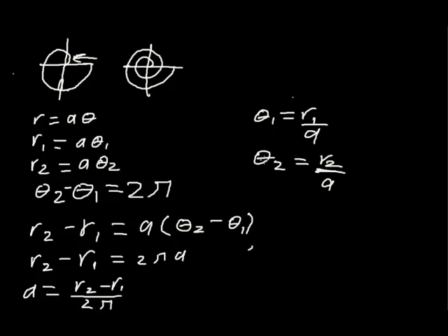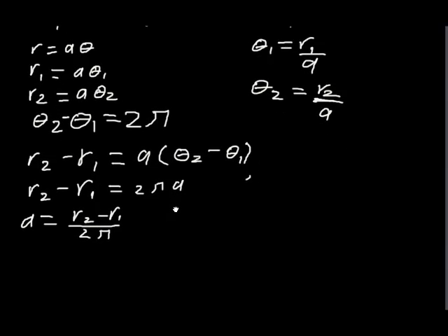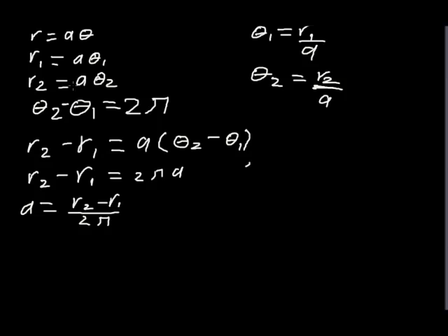So now what we're going to have to do is convert this equation into a parametric representation, because this is a very nice simple equation in polar coordinates, but SolidWorks doesn't support polar coordinates, so we're going to have to convert that to parametric form. So we're looking at r, the radius, as a function of the angle theta.